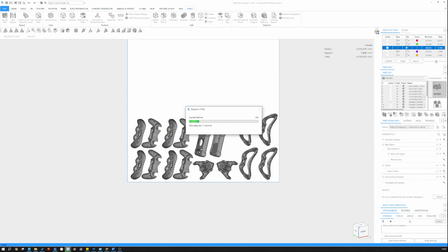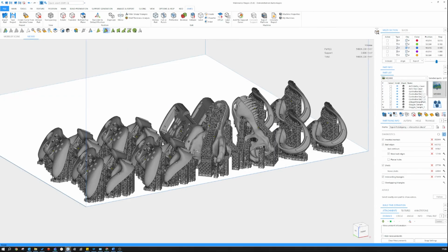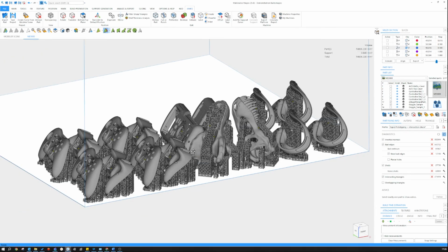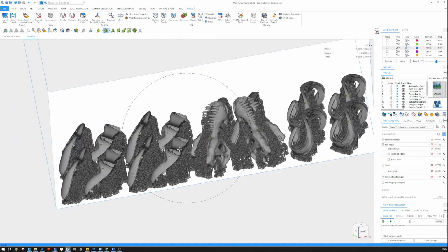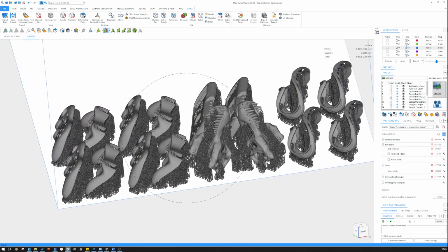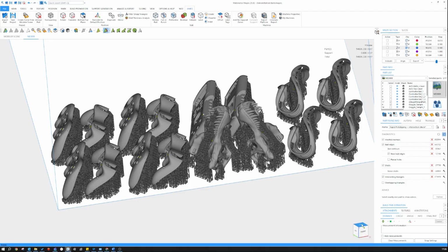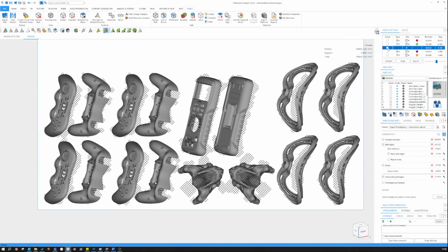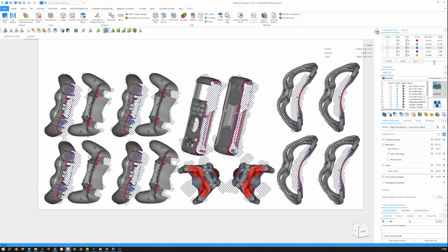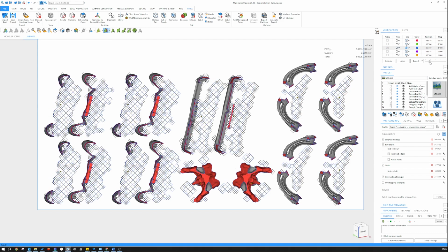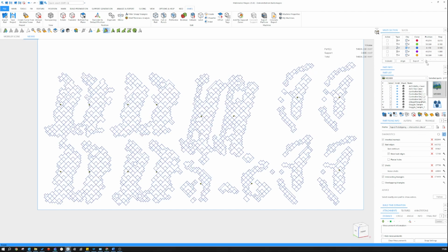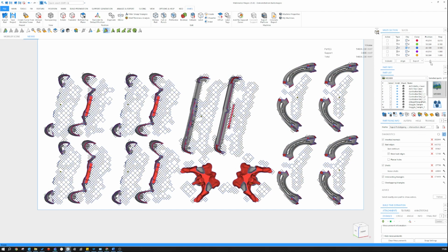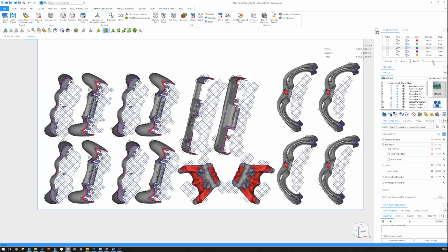Now the supports are created, we can review their suitability for build. Make sure all the starting points and shallow angles are supported and any taller parts are sufficiently braced and don't look like they'll wobble or move during the build process. It is important that you are happy with the design of your supports. You may need to adjust part orientations and supported areas multiple times before committing to starting a build. This is normal practice and should not be skipped in the interest of speed.